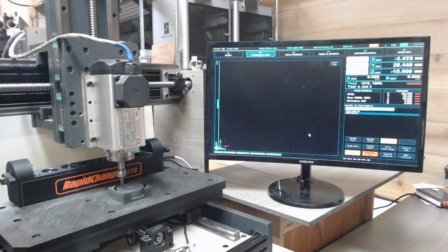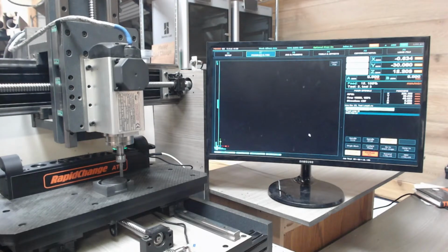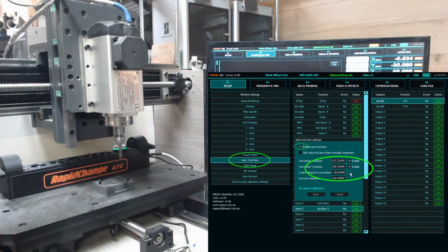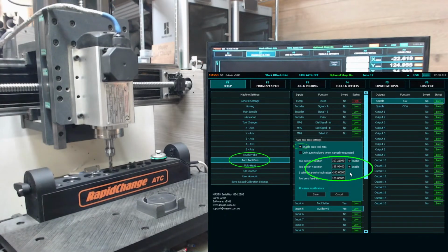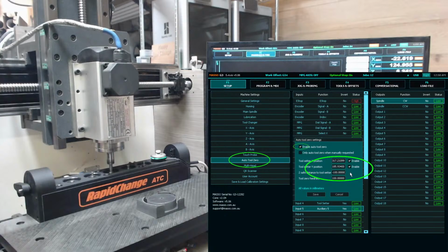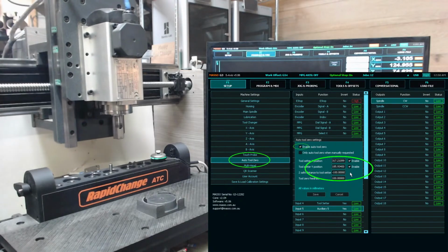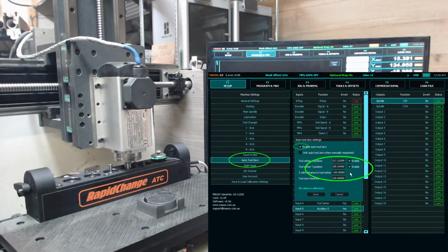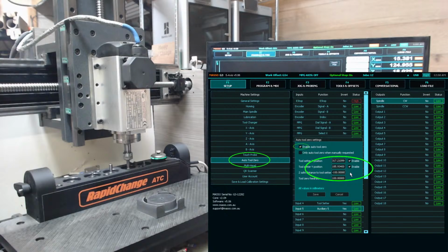And so from there, you would go in and set up the auto tool changer in the F1 setup screen. Pick auto tool 0, and then come in here, enable it, and put your X and Y positions in machine coordinates. Enable those. Give yourself a place to start the probe from and how fast you want the feed rate to be. Save it.